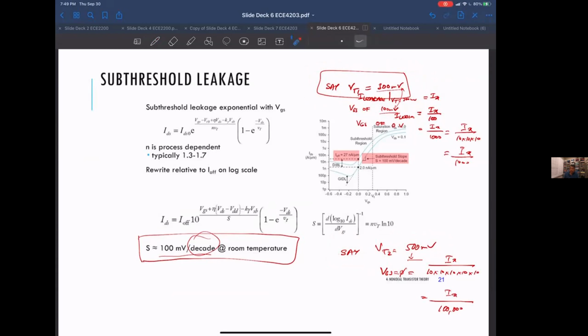So why don't we just crank up the threshold voltage to kill off this subthreshold leakage? Well, the problem is now we've got a trade-off versus the on current. We know it's not exactly this, but roughly, for an on current, all things being equal, the lower the threshold voltage is, the more on current I get.